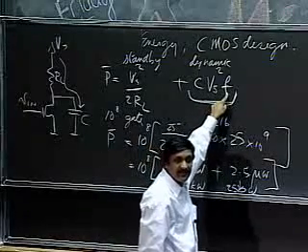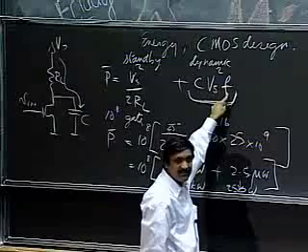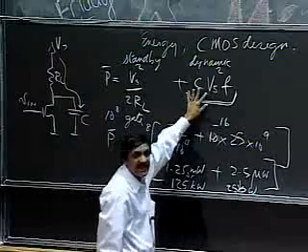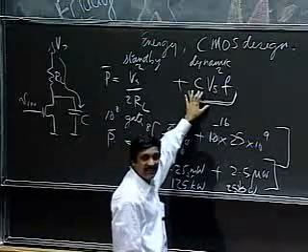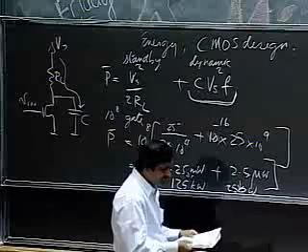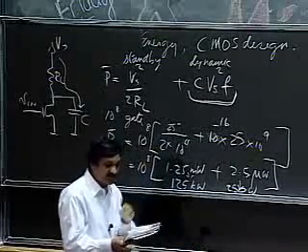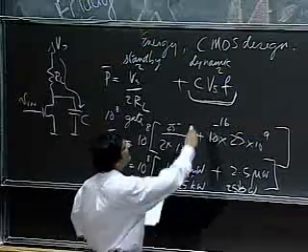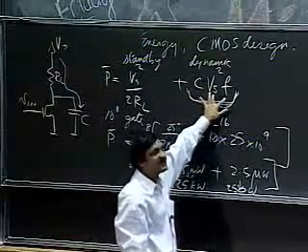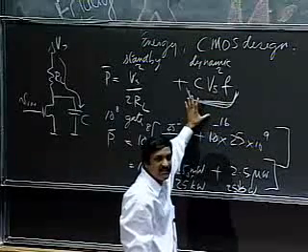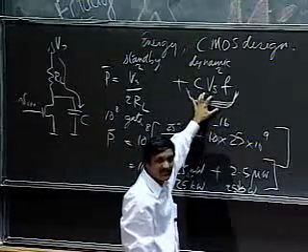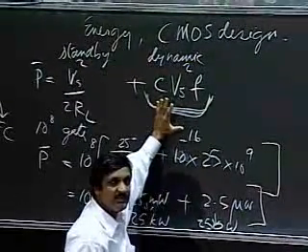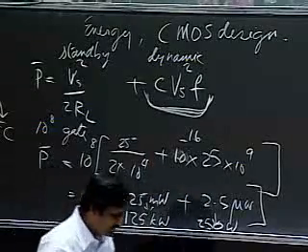Per megahertz, that's because the power is a multiple of F. Second, it's per gate, so this is the power per gate. As I have more gates, I just have that much more power dissipation. It also says power supply voltage in the range of 0.7 to 1.3, right next to the power expression. So you can see why they tell you all of that, because the voltage, the frequency, and the number of gates all come into the power equation. This really simple expression is amazingly close to what people use for the dynamic power in chips.